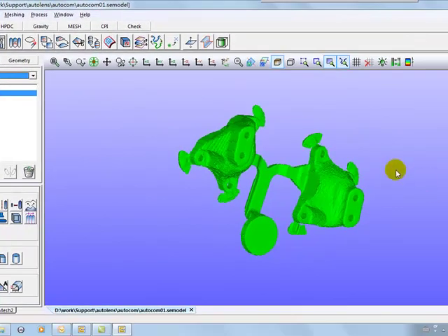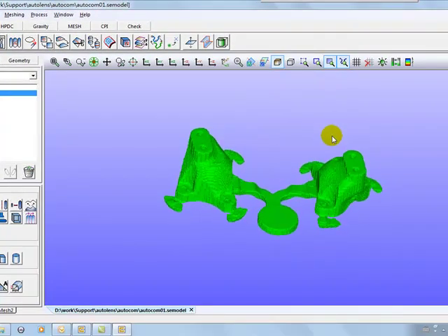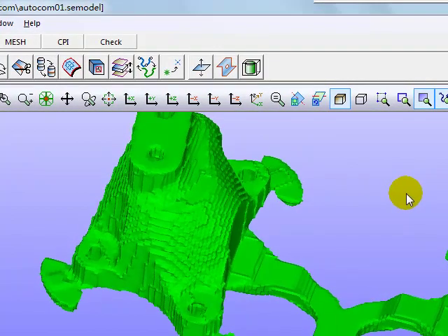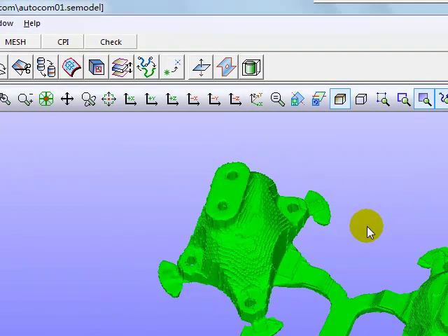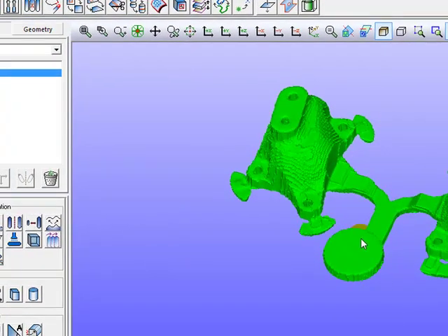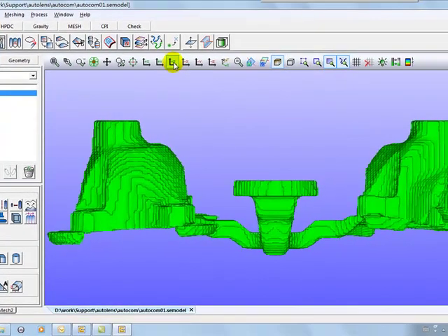Cast Designer CPI uses the object concept for model setup. In this case, any physical attribute should be applied to the objects. This provides a very flexible method for part exchange. So we need to prepare some objects before the CPI setup. The first object we need to create is the nodes of the piston.